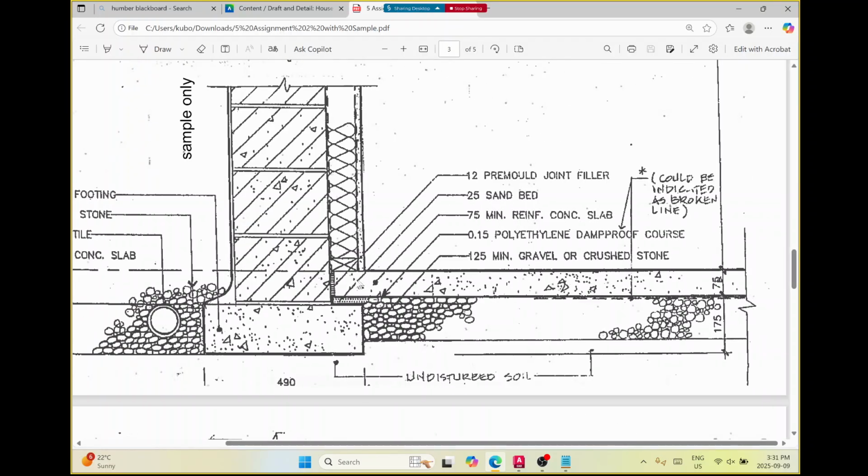Now we want to go, it doesn't really show, see here in the drawing it just kind of cuts off. We have another break here, because if we kept going it would be a building section. Sometimes you draw the whole building as a slice, but really we're just interested in the wall. So they're just showing us a little bit of the floor, and then they cut it off. So I'm going to grab the line we have and stretch it a little bit the other way. And you can kind of eyeball how far you want it to go.